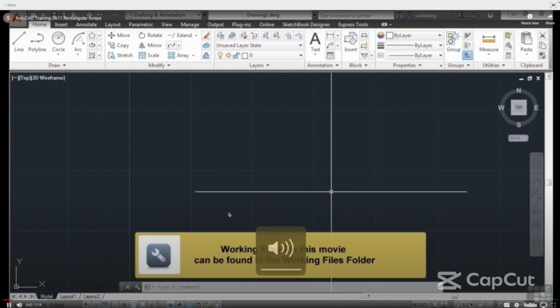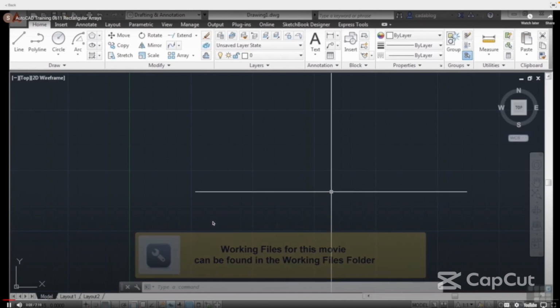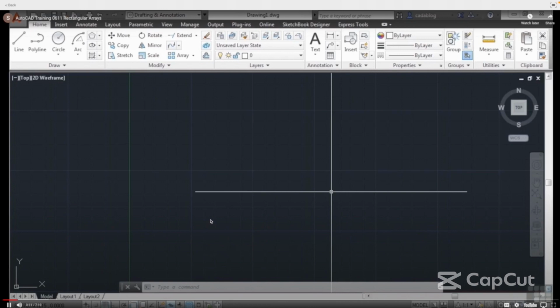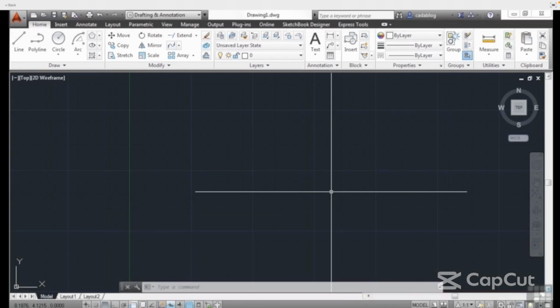Though just as similar to each other. The fillet command creates a tangent arc between two lines. The chamfer creates an angled line between two lines. The processes are similar. You start the command, you define the arc radius for the fillet, or in the case of the chamfer, you define the distances for where the chamfer lines will go, and then you pick your lines.